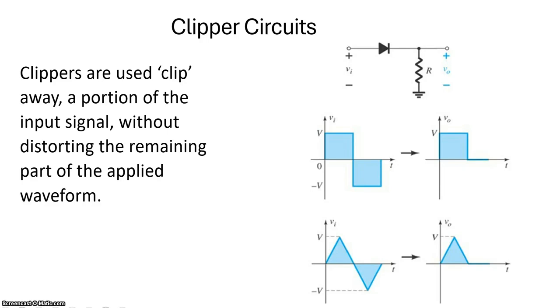This section discusses the application of diodes as clippers, a wave shaping ability of the diode. We have studied already about rectifiers and the half-wave rectifier. The half-wave rectifier is the simplest example of a diode clipper, with one resistor and one diode. Depending on the orientation of the diode, either the negative half cycle or the positive half cycle of the output voltage is cut.